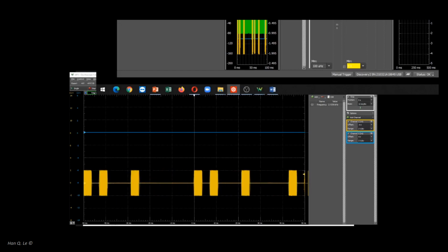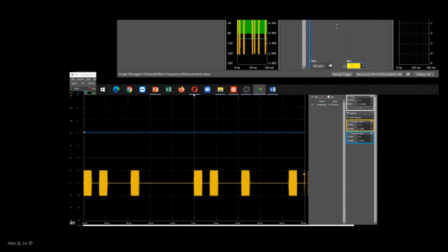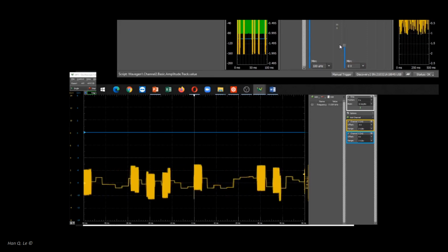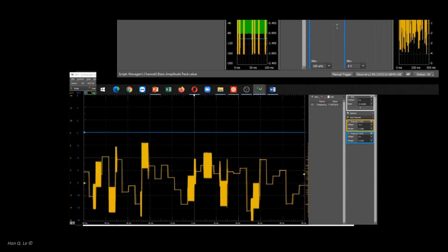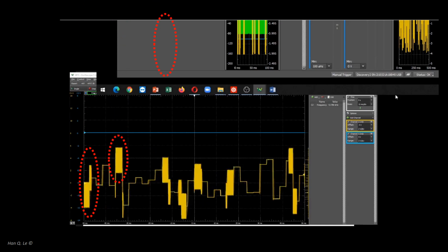Consider the modulated signal with added simulated noise. The noise amplitude is slowly increased. The signal plus noise appears random. However, one can still distinguish the signal from the added noise based on the carrier oscillation. As shown, what is needed is a circuit that can separate the portions of the total signal with carrier, encircled with red dash, from those without.